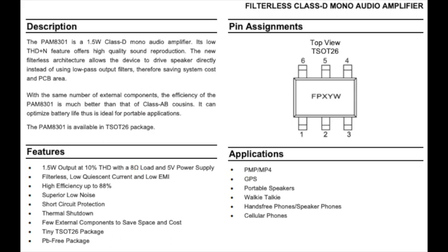The fourth category is functional description. Here we look at pin configuration, pin functions, function tables, block diagrams, timing diagrams, signal descriptions, input-output waveforms, and functional diagrams. This information is necessary for designers to understand how the component operates and integrates into their system.